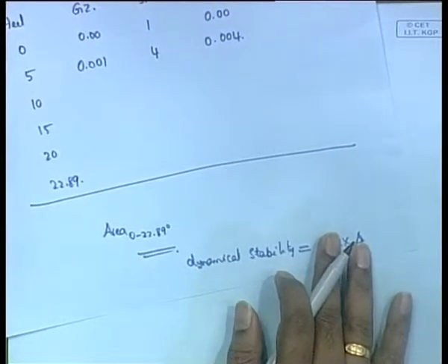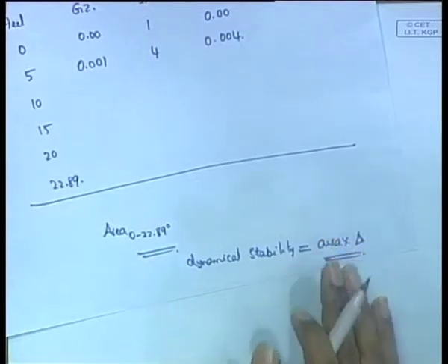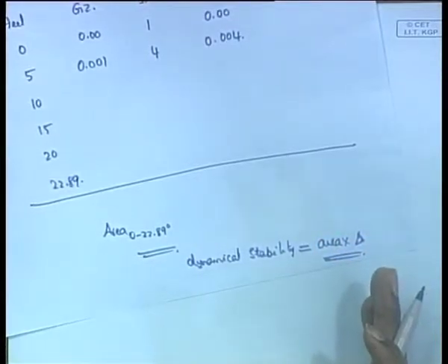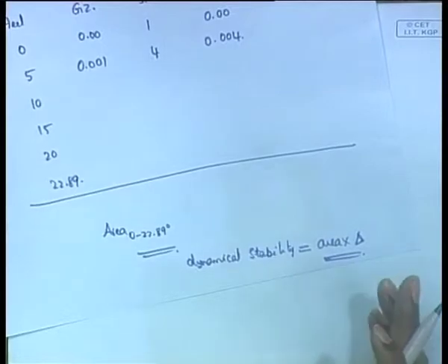So, here we found out how to find the deck edge immersion, that is very straightforward, just geometry you can get that. Then next is you have to know for a box shaped barge how to find KM, how to find BM, two things, because nothing will be given, that formula has to be known. Other than that, of course, there is no difference. The only thing is, in this case you get GM to be 0, there is no special formula or anything to be applied here. In the wall sided formula, GM becomes 0. So, the problem becomes simplified.